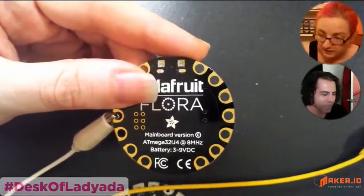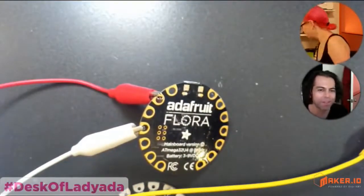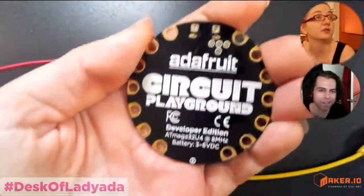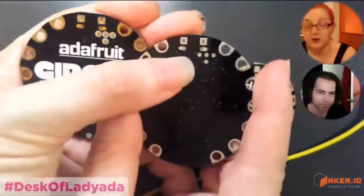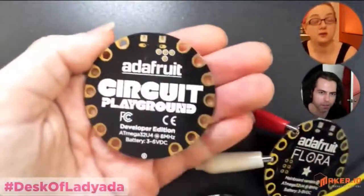When we get to Rev C, we copyright everything. Anyways, that's what it means. Here you can see this is Circuit Playground, and C compared to B here. Put revision codes on your PCB, it's a neat PCB trick. Just don't freak when you see if we ever get to revision R. So you can see I actually made these little pads a little bit bigger here. Those are the programming pads.